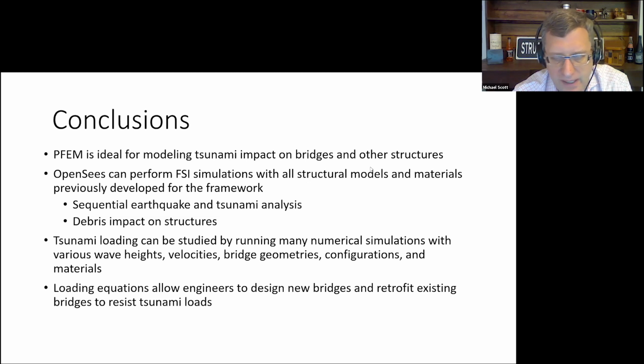Well, definitely the flow height, the flow speed, the bridge geometry, the fluid density. And bridge geometry accounts for a lot of things. We looked at wider and wider bridge decks, more girders, spacing between girders. We looked at the effect of trapped air a little bit, and that's something more that Dennis Estrada and Ian Buckle at University of Nevada, Reno, did some experiments on.